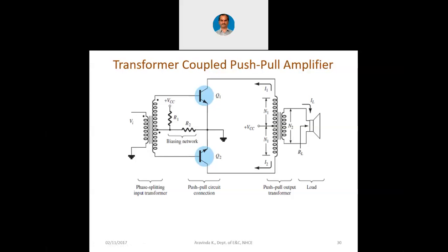Let us say in an industry or a factory there will be a morning bell for the morning attendance and even an evening bell for the closure of the work. So they can have a 1 kilohertz oscillator there. 1 kilohertz RC phase shift oscillator or a Wien bridge oscillator, because that is meant for audio applications.